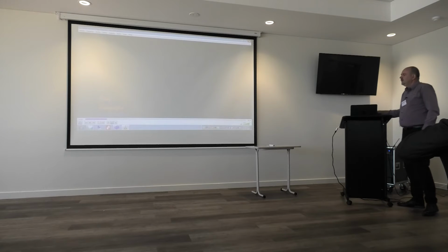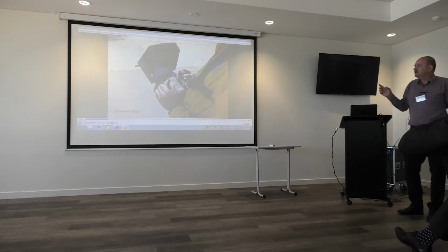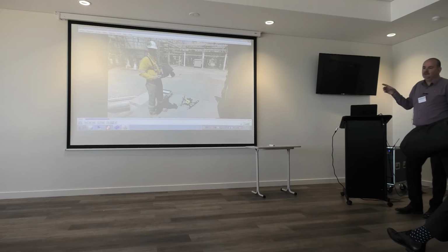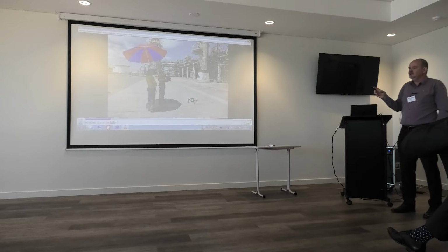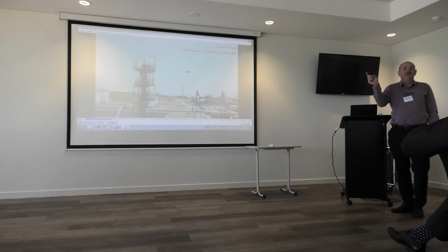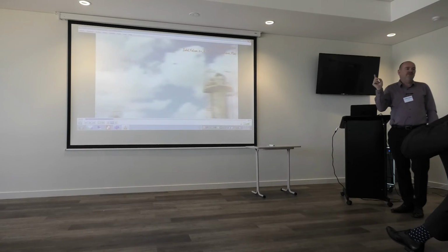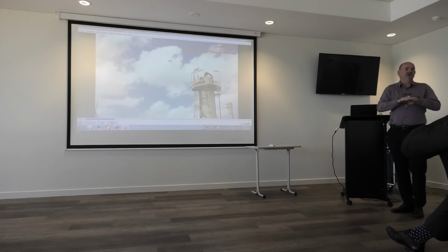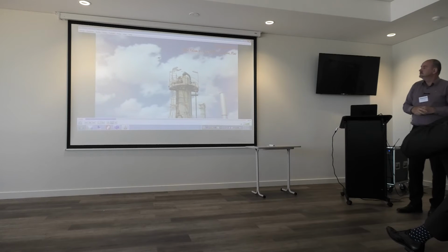Aerial photography. We then use drones. Applus has a very large drone company based out of Adelaide, and we use the drones to capture aerial surveys. One of the advantages of drones is that we can use GPS tracking. So we can do a drone survey of a building, track that GPS track, and do exactly the same track next year and then the year after. Then you can overlay the information and look for differences between structures over time.